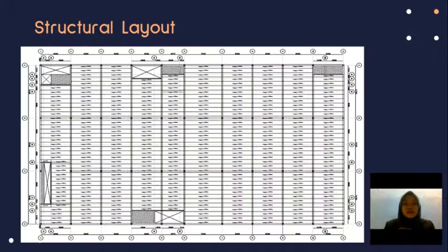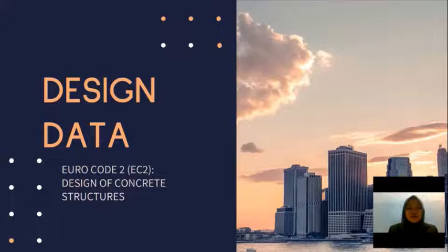Next, this is the structural layout of the building that was produced from AutoCAD software. It can be seen that in the layout, the cast in situ part were hatched. Next, the design data were mostly referred from Eurocode 2, which is design of concrete structures.